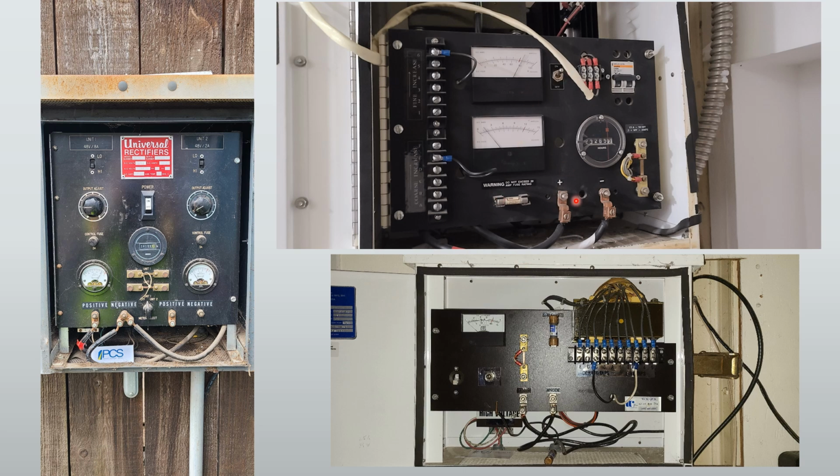More examples. This one has a toggle switch. So the voltmeter and the amp gauge are combined into one. So you got to be careful which one you're reading. Volts on top or amp on bottom. These switches can be finicky. Sometimes they stick. And if you press it for the first time, sometimes you'll get a reading of 0, which is a false reading. You got to jiggle it sometimes to get the actual reading. Because you can take your direct reading, see there's a voltage output, take your shunt reading, know there's an amp output, but then it doesn't match up. So sometimes it's just a faulty switch.